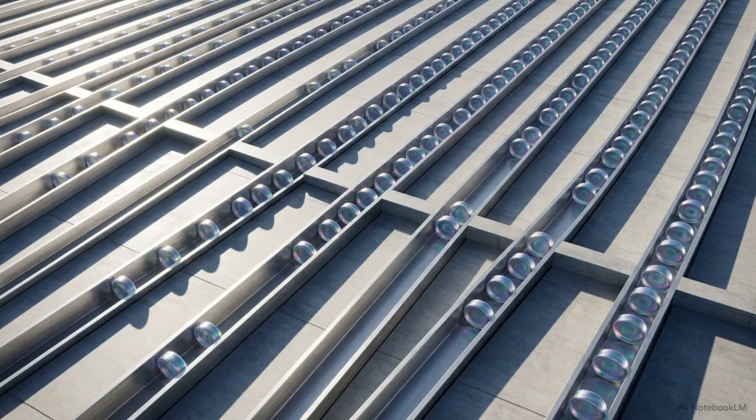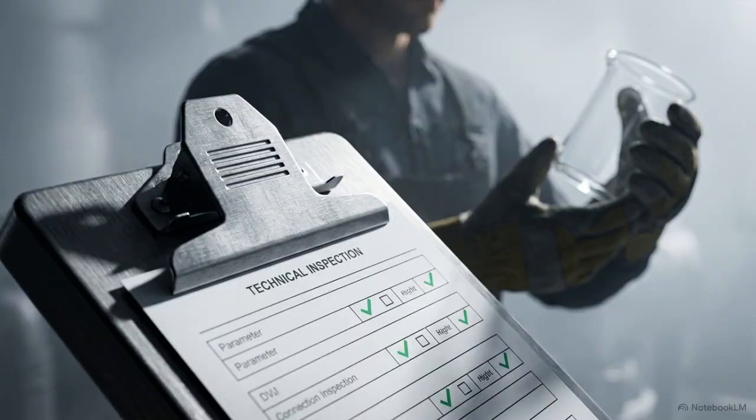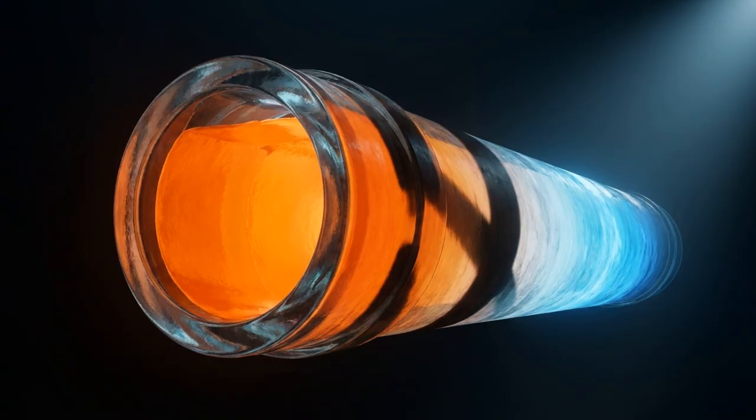By enforcing a completely uniform residence time for the reacting fluids, chemical engineers can guarantee the highly consistent product quality required to meet strict pharmaceutical GMP compliance. The plug flow reactor remains the ultimate physical manifestation of spatial geometry directing the precise mechanics of chemical conversion.